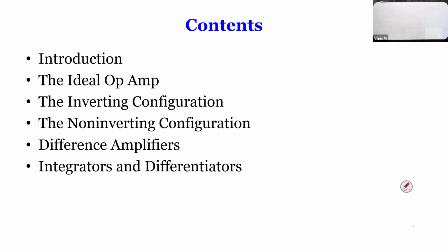And then within the ideal op-amps, we talk about three kinds of amplifiers. So there's inverting. Inverting by the name means reverse, right? It means negative. And the non-inverting means the positive. Then there's a difference amplifier, sometimes called differential amplifier, and sometimes called difference. Between difference and differential, there's no big difference in meaning. Basically, you take the difference between two inputs. But differential sometimes means they don't have a common ground, and difference could mean that I'm taking the difference, but the two actually share the common ground. So that's probably the only difference you can look at.